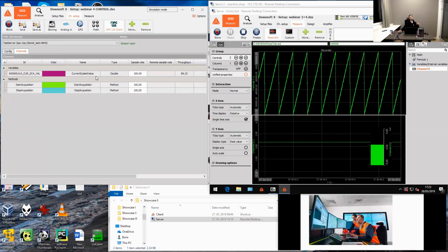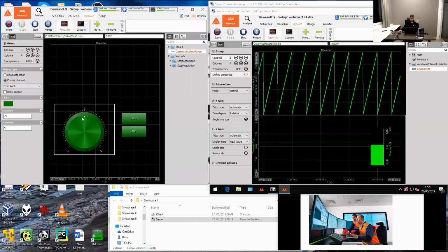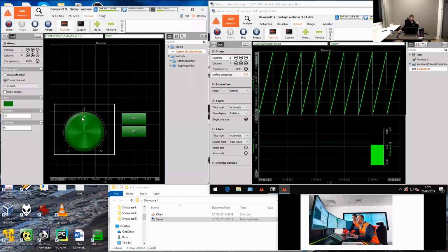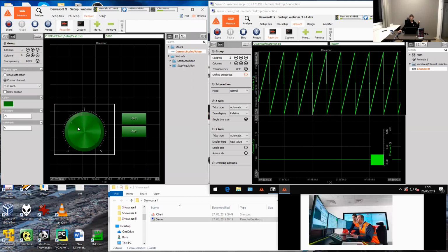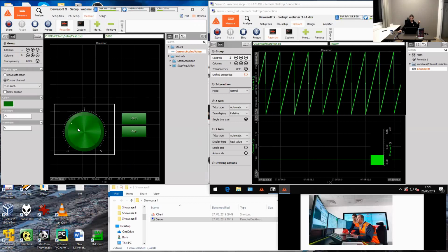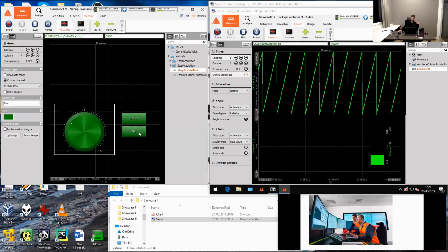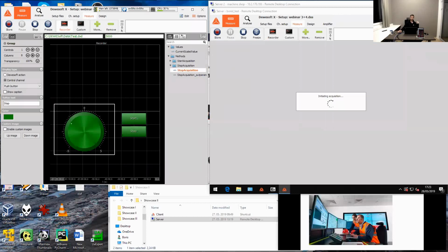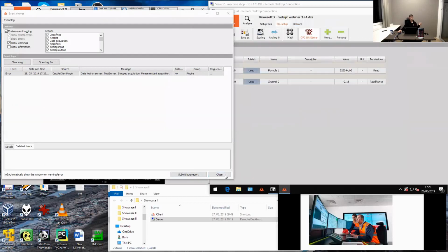Okay, so we've registered this variable to OPC client and two methods that are exposed by OPC UA server. So these are start and stop acquisition. So let's check how this works. On client side, I can change the value, and you can see on the server side the value is being changed. Then I have two buttons, start and stop, so I can stop acquisition, and now I can expect an error on the client because monitoring has been cancelled.